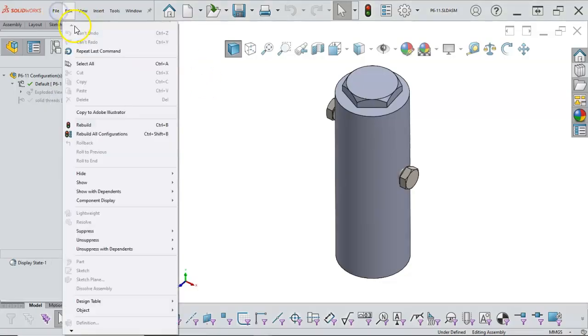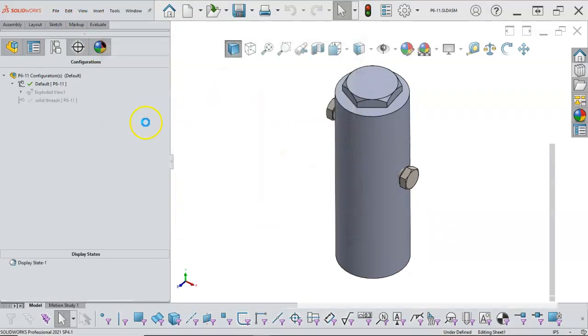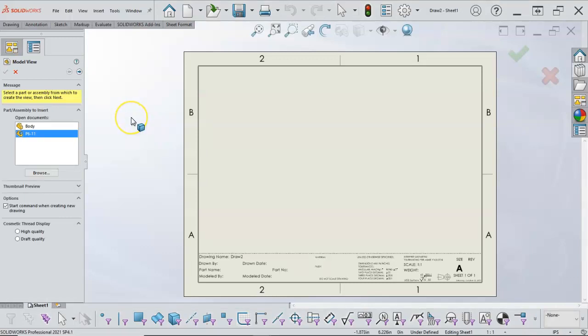For the drawing then, we'll go into New and the My Landscape. Again, if you haven't produced this title block, use the standard SolidWorks A or B size. What I'm looking for is the creation of the views and applying the dimensions. As you progress and become more comfortable with the software, then you'll want to build in these other items, being able to utilize the layers, being able to utilize the title blocks, the sheet format, and the document template.